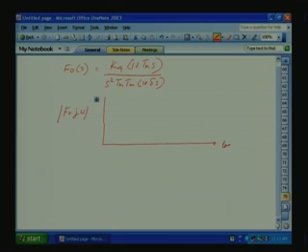This is our log omega, this is our gain, and this pole at delta is 1 by delta. Choose Tn from the last example, we know Tn is equal to 4 delta. So, 1 by Tn will be somewhere here.